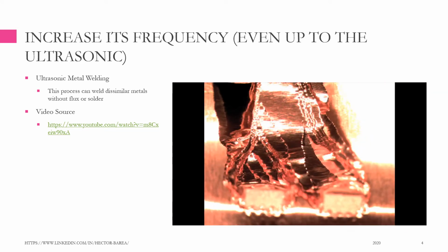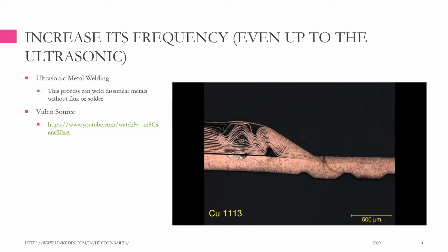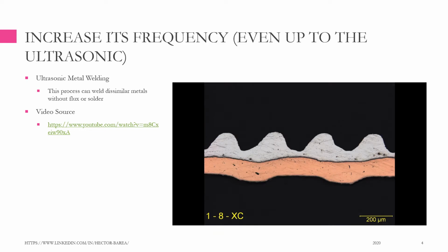Here we see a multi-layer foil-to-tab joint typical of internal battery cell connections with a cross-section of that same joint. This cross-section shows an aluminum-to-copper weld for a battery tab application with tooling impressions that are typical of the process.